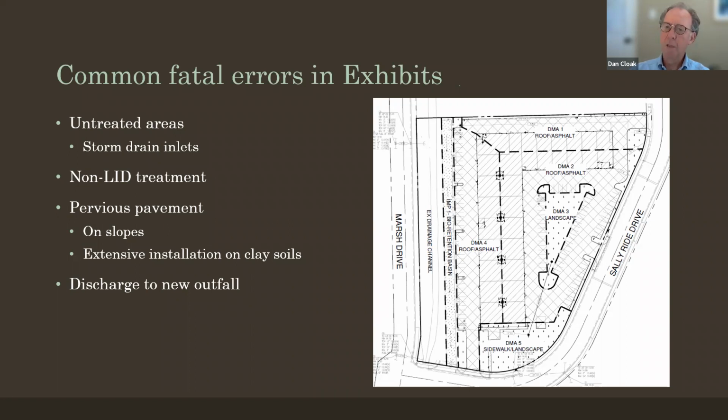Either it's an extensive installation on clay soils, and the intention is to drive on that pervious pavement, and the pervious pavement that would be required in order to hold up structurally with no compaction at the bottom of the excavation is going to have a very, very deep section.